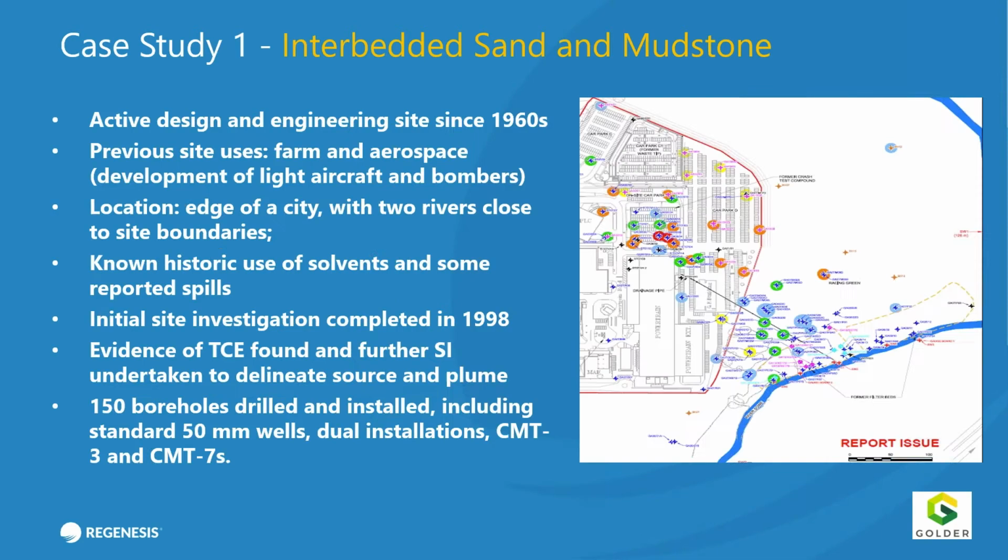So as part of our, I'll step back one, as part of our remediation strategy, we were suggesting that, let me get my laser pointer, source zone treatment using an appropriately soluble electron donor should have occurred here, and then an in situ PRB comprising Plume Stop and another electron donor called HRC was to be installed along the down gradient edge of the site to protect the stream.